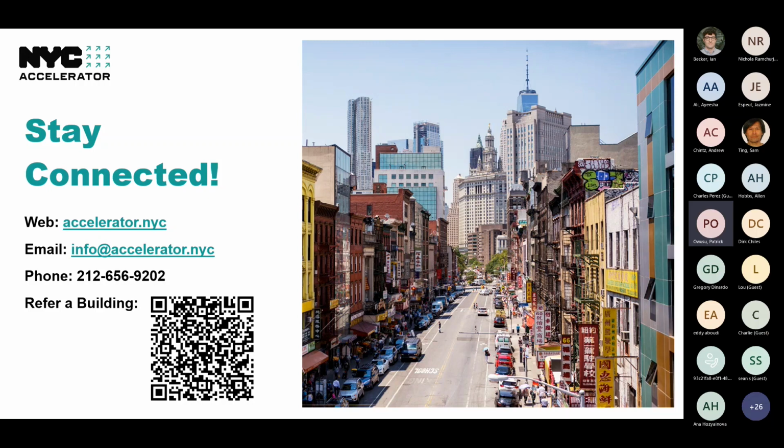And white roofs can be used along with solar, and that can be part of the preparation for a rooftop to be solar ready. That could potentially be included within the solar scope itself, like a white reflective coating, in order to prepare for having the solar installed. Solar panels do work best when it's cooler, so having that cool roof would help to optimize.